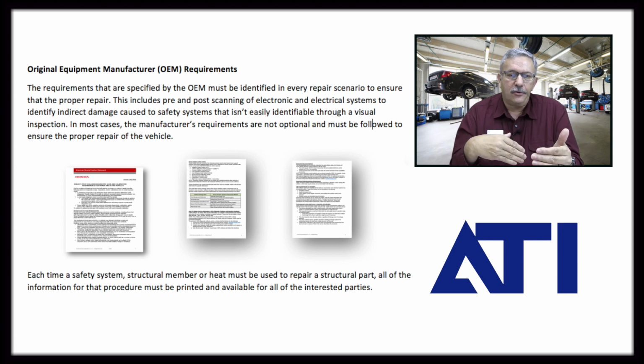And in almost all cases right now, the manufacturers are telling us that in any collision where parts need to be replaced, there must be a pre-scan so that we can properly diagnose if any of the electrical or electronic systems have been compromised in the loss. That's hugely important to us.